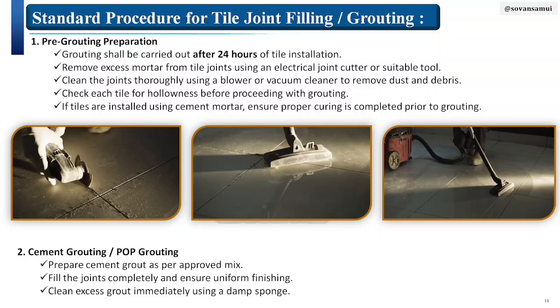And first you can see the image. If excess mortar is available at the joint, then you should take it out or clean the joint with an electrical joint cutter or suitable tools, as you can see in the image, and clean those joints with a blower or vacuum cleaner to remove dust and debris.